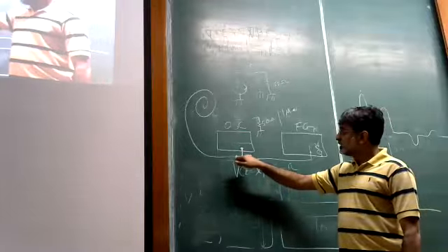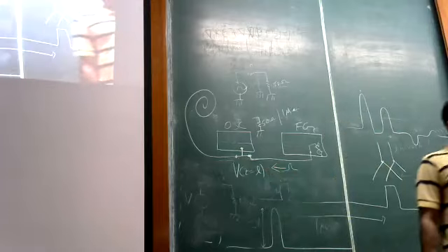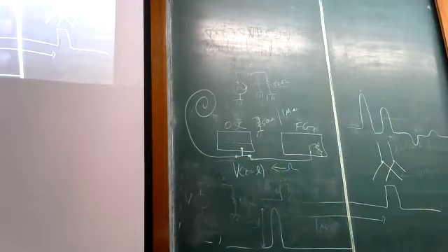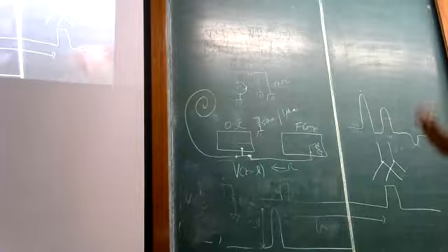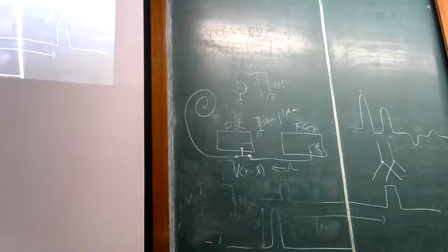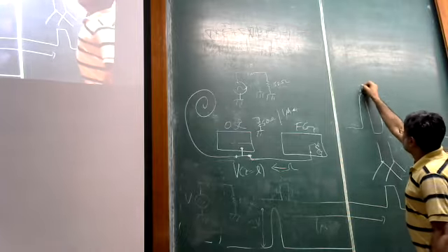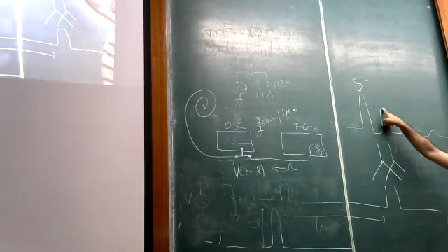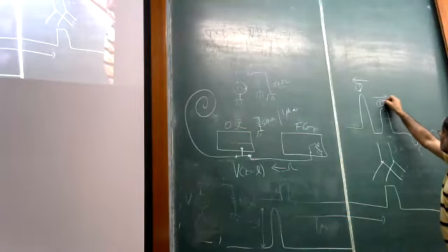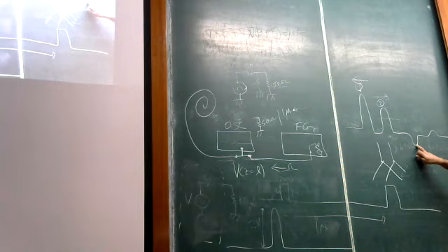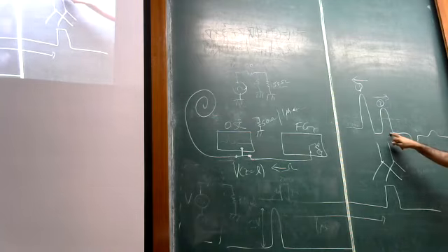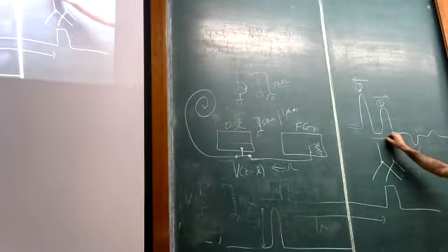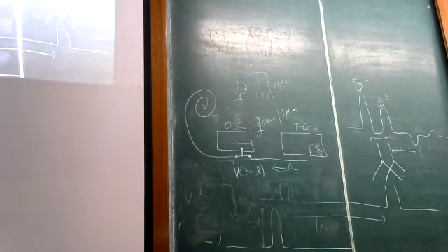So what you're going to see is that at this point, there's going to be a reflection, and the oscilloscope will measure a reduced one. The next pulse you are seeing is the pulse which has gone back a second time, right? That's not this pulse here. This is the first one which is traveling in this direction. This is the second one which is traveling in this direction. This one is the reflected wave of this guy traveling all the way back. So it of course takes the same amount of time, so the time gap between these two and these two is the same.